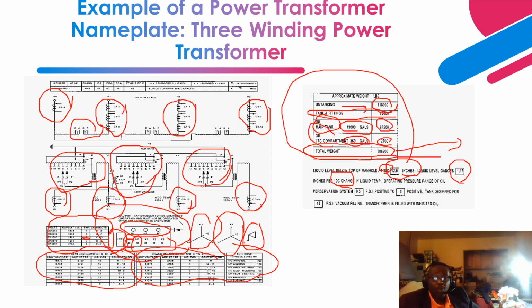Likewise, if you have the transformer contracting in volume during winter time, right? When the transformer load goes down, the transformer contracts in volume. So based on the outside temperature, right? The changes in the level of the oil can be determined based on the 10 degrees C change that has occurred. That is, the transformer outside temperature is measured utilizing all the oil temperature indication devices that are located on the transformer.